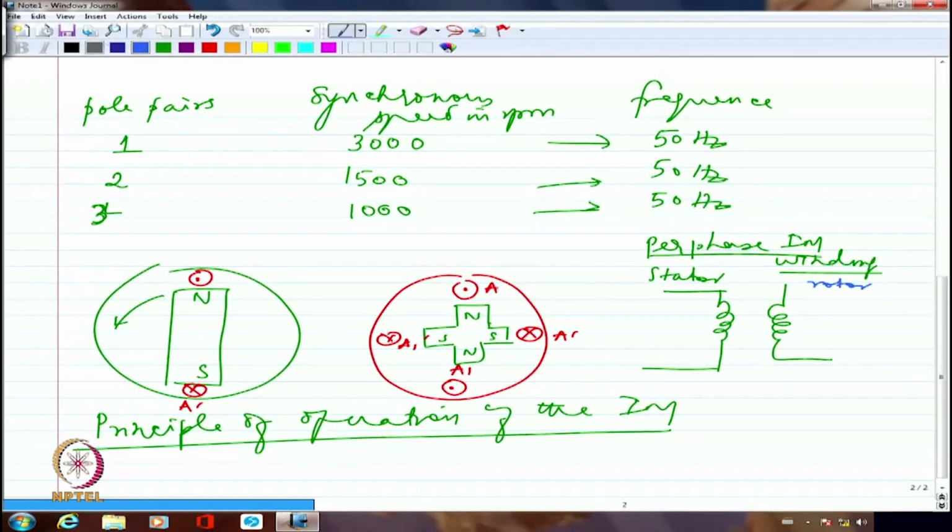Okay? Now, I told you that it has to be short circuited, so I am short circuiting it simply. Right? I have applied 3-phase currents to all the 3 phases of this induction motor's stator winding. So I have just connected a voltage source and applied the current. So the current drawn should actually be enormously high.